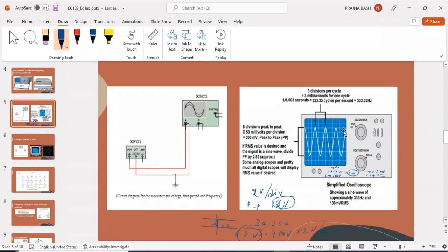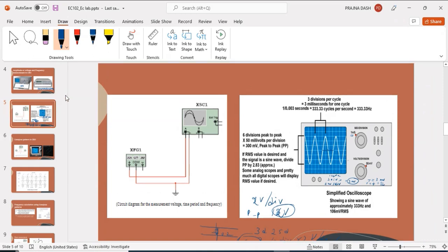Whenever we represent the signal for calculating frequency or amplitude, the representation is the value or voltage of the signal with respect to time; we plot the signal and observe it. But the second objective of your experiment is measurement of an unknown frequency and phase of a signal by using the Lissajous pattern. That is another kind of representation of signals on the CRO screen.